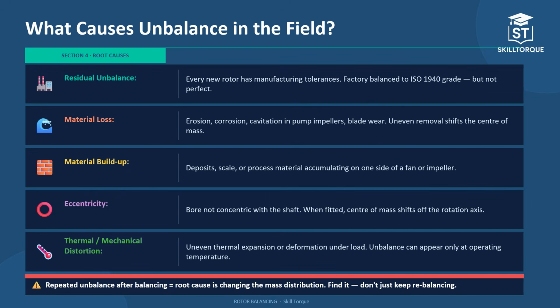Okay, what can be the reason for the unbalance? We know what is the unbalance, right? That is the uneven deposition or uneven wear of the rotor, right? That will create the unbalanced force. Okay, so what can be the reason for that? It can be the residual unbalance.